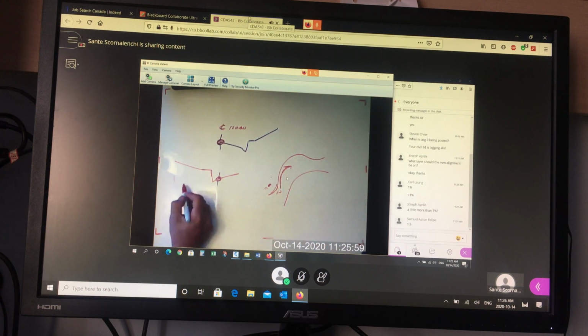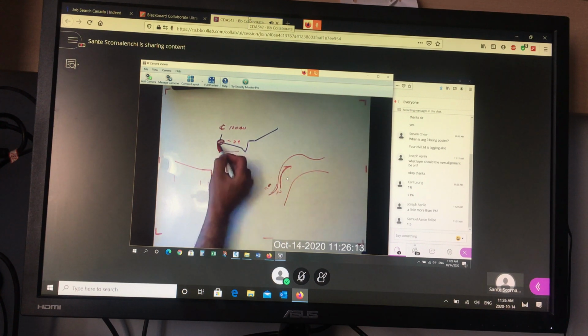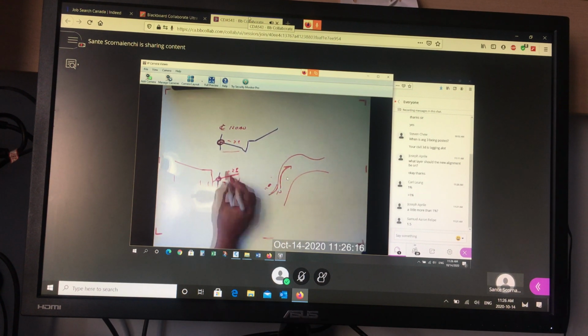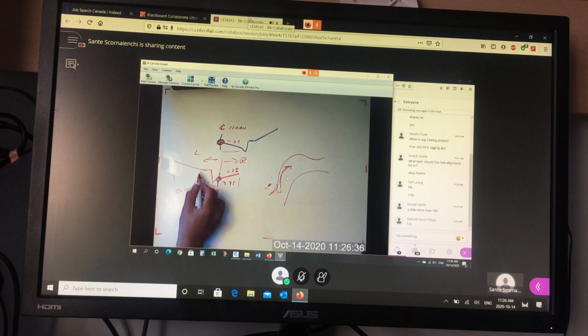So now I have to remember how wide each piece is and what the slopes are. Relative to center, this is going to be, if you remember this piece, 3.95, but now I'm going up. It's not going to be negative 2%, but I'm coming out of the gutter, it's positive 2%. And it's on the right side of the assembly point. Everything else is on the left side. Okay, so if you remember these widths, the width of the gutter, 0.3. The width of the face of curb, 0.05. That's this dimension. The width of the top curb is 0.15, and the width from the back of curb to the street line was 5.55.